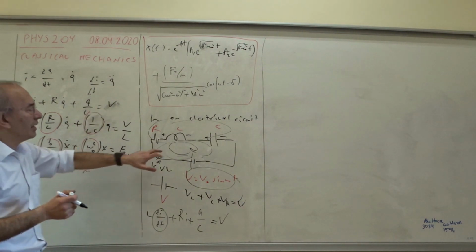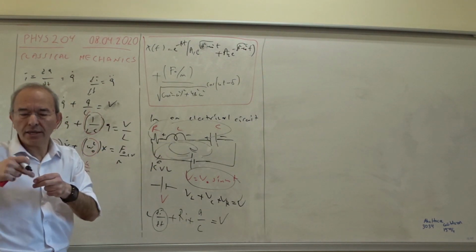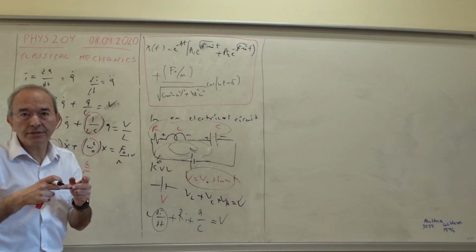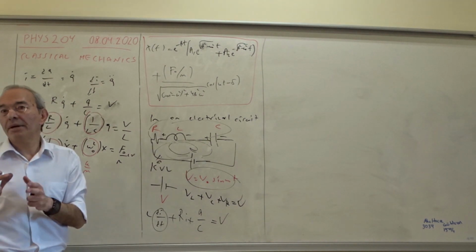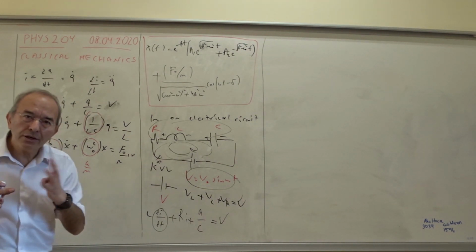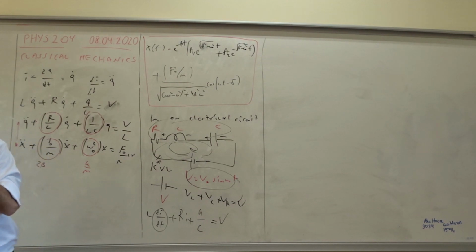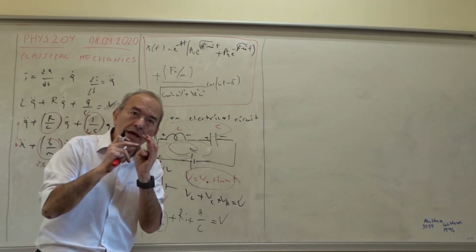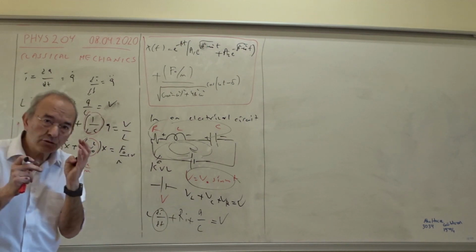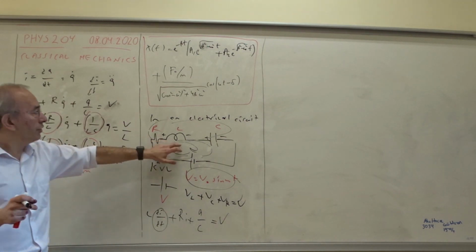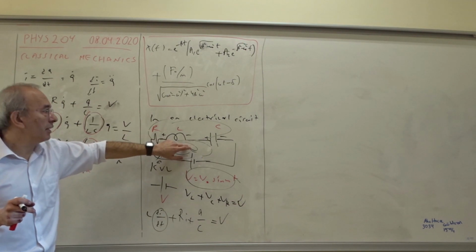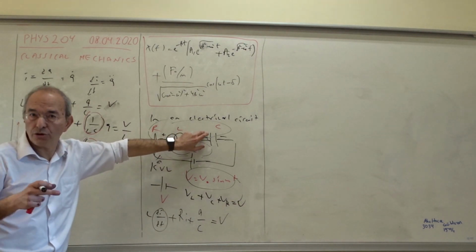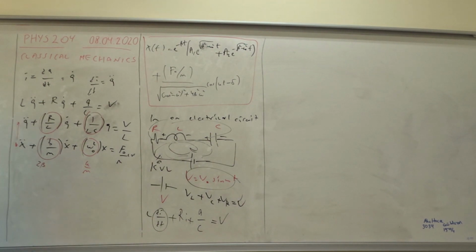So if you have just an LC system, one inductor, a solenoid, and a capacitor only, initially the capacitor is charged somewhat, then they make oscillations. Charge is going from one element to the other, and then coming back. It makes oscillations back and forth. So this kind of oscillation in the LC circuit, inductor and capacitor circuit, is almost the same as the potential and kinetic energy terms in the mass spring system.